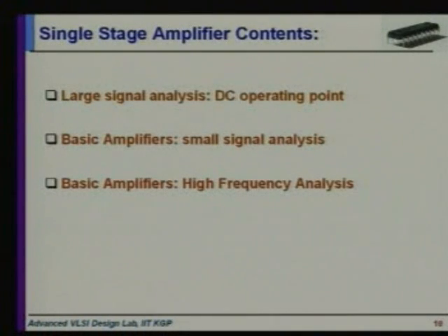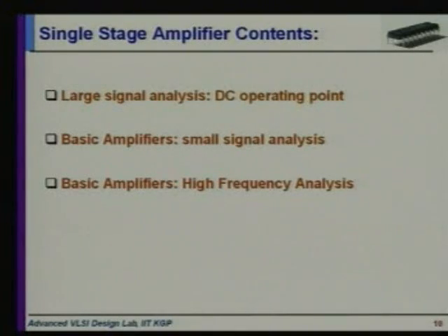Now what will be the design flow whenever we are trying to design a single stage amplifier? If I know the circuit, then how will we approach it to meet our specification? This is nothing but we have to find the DC operating point, then the small signal analysis of that particular amplifier, then high frequency analysis if we need.